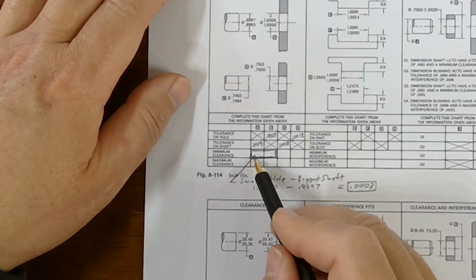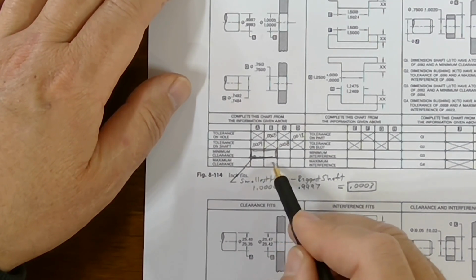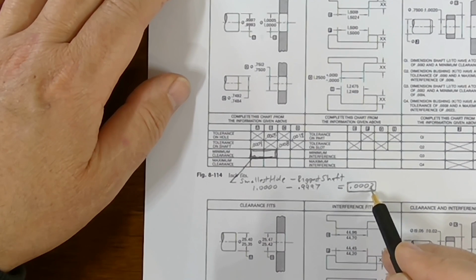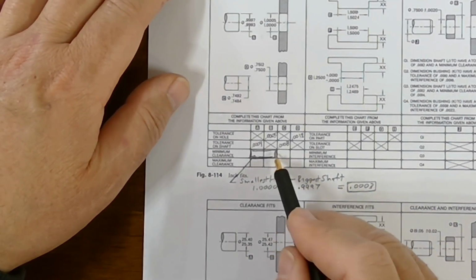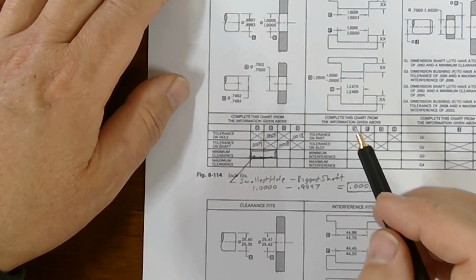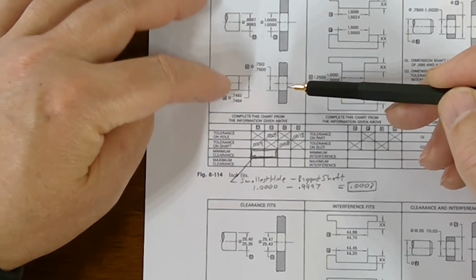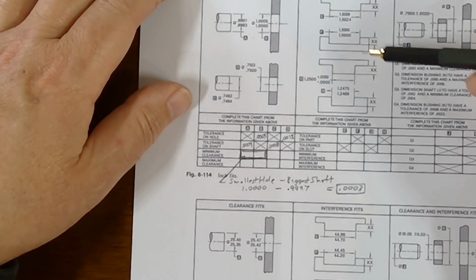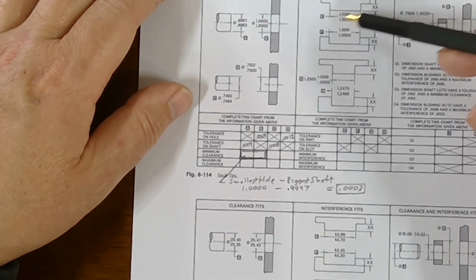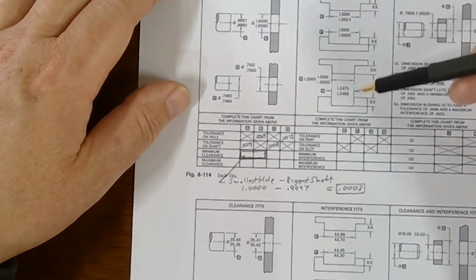Then calculate the maximum clearance, which would be this box in here. These would have the same answer. And then the range between this and this 0.003, which goes in here, would give you the tolerance on the clearance. Then do that again for this other guy sticking in there. And this thing here, it's interference. They just haven't used shafts and holes. They've used these little bumpy things stuck into this little groove, but it's still an interference fit.